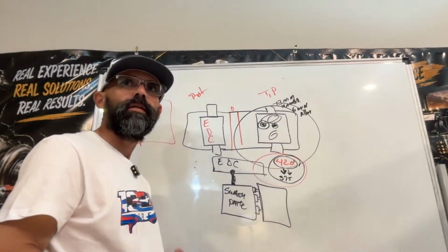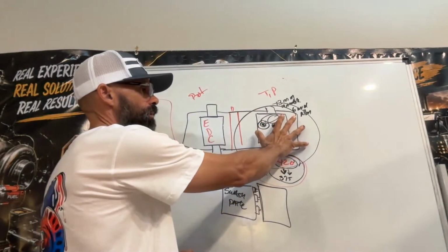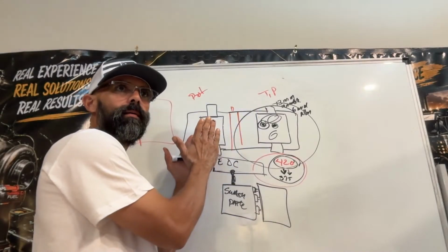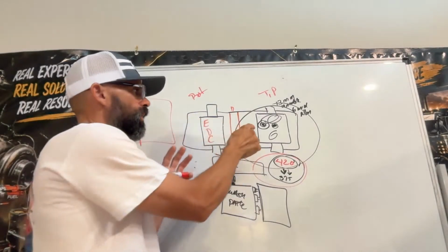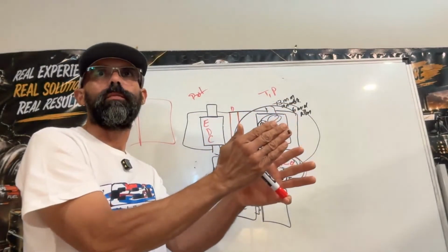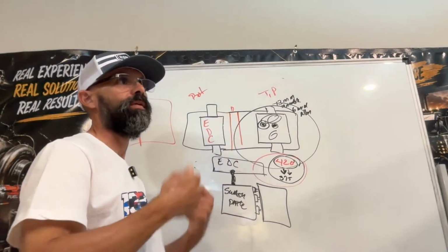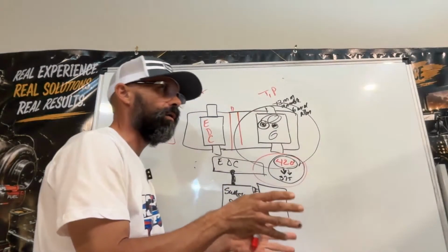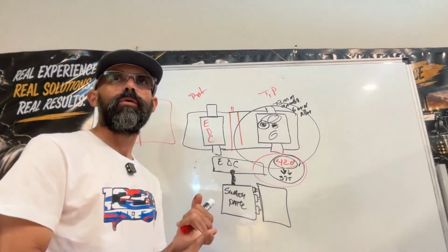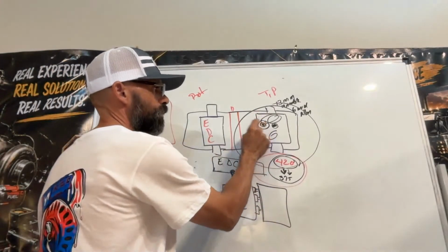As you spin it 360, if you keep spinning it, you're gonna see that if it is on the thrust and pullback, your carriage is gonna start creeping back and then pulling back faster, because you're changing the angle of the swash plate. You're taking it out of neutral. But if you go the opposite, if you tighten it, you're gonna increase it, and you're gonna take it also out of neutral, and then your carriage is gonna go forward by itself. So if you have a carriage that goes forward by itself or creeps forward without touching the joysticks, this is what you gotta adjust.